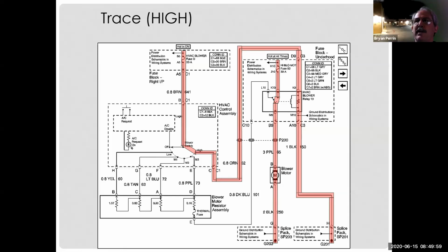As long as we're flowing current through that leg of the circuit, I can only drop voltage through the resistor with current flow. So in other words, if I turn it on here to M1, I drop voltage here, and drop voltage here, but at B, I would not drop any voltage because it's not a complete circuit. If I turn the dial to M2, I'd have system voltage at A, I'd drop the voltage to D, drop the voltage to E, but I'd have full system voltage at C and B because they're open parallel legs that don't have any current flow.